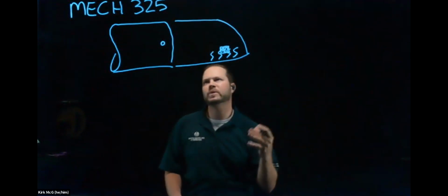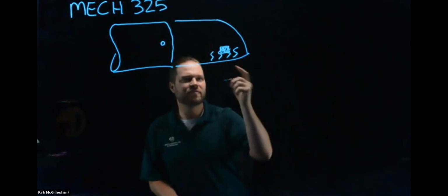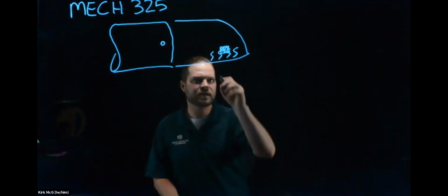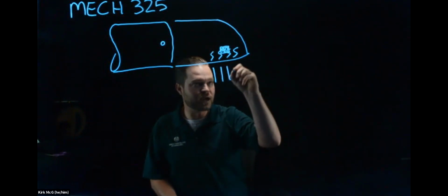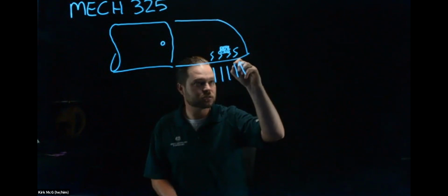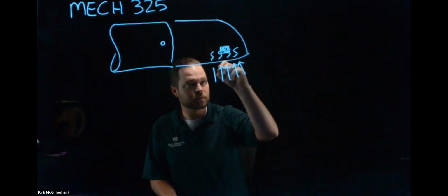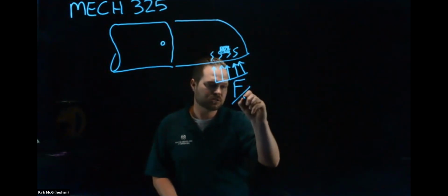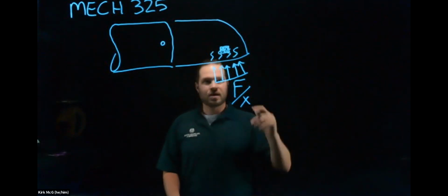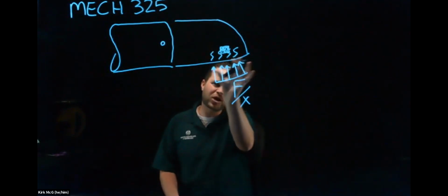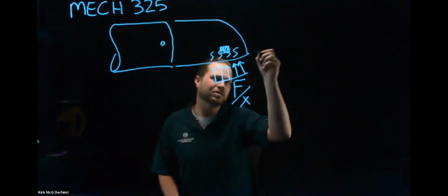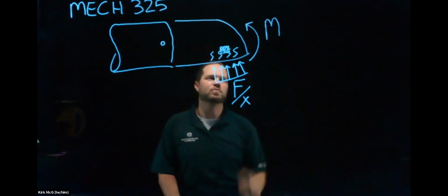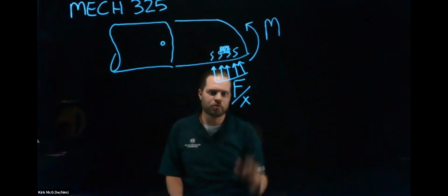So let's just think about what happens. You have a finger, it's grabbing. Let's imagine if I grab something and it's delicate, I want this to be really high resolution. You like having good dexterity. So let's say there's going to be some pressure or distributed force applied at your fingertip. This is some force over some distance x, okay? And then you're grabbing it, it has a little friction in here, it's hard to pick up, it's a little heavy, so maybe it applies some type of moment on your finger. So we have multi-axial loading, okay?